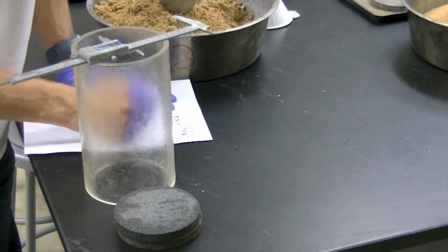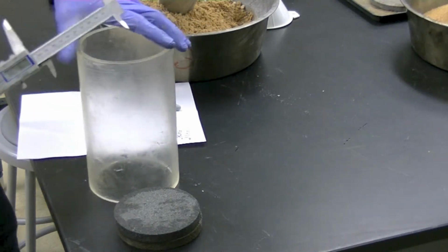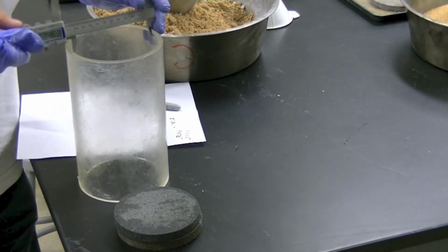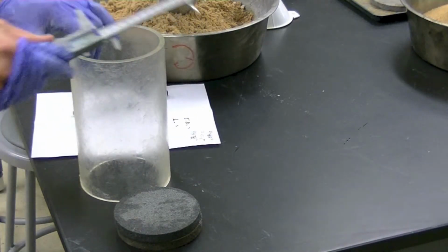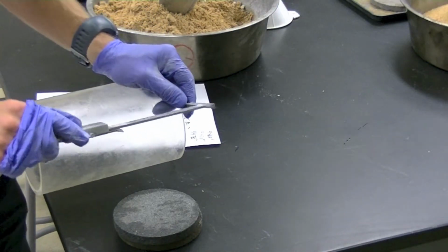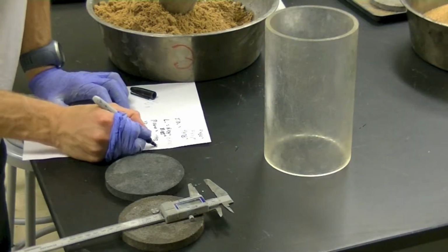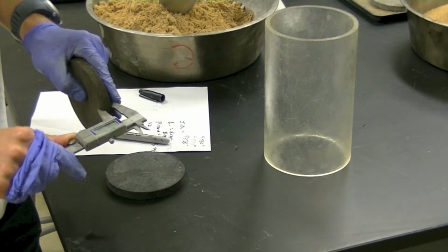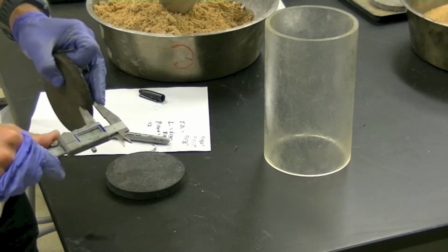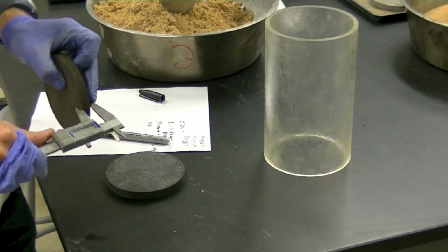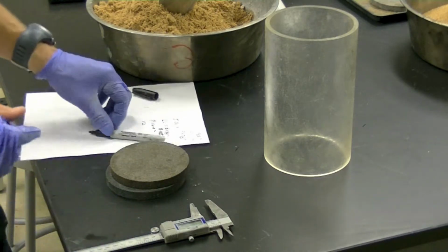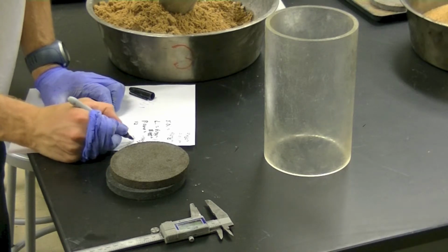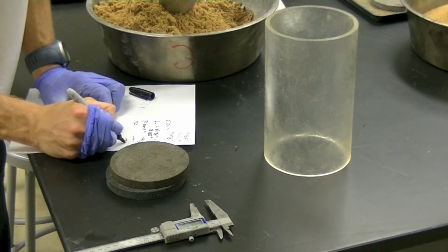We must first take all of our measurements before we begin assembling the permeameter. Measure the inner diameter of the tube. This will later be used to calculate the cross-sectional area of our sample. Next, measure the length of the tube. Measure the thickness of the two porous stones. The sample will be molded such that the length is the tube length minus 2 times the thickness of one porous stone. Thus the sample sits between 2 porous stones that are flush with the ends of the tube. Take and record all these measurements to the highest degree of accuracy the caliper is capable of.